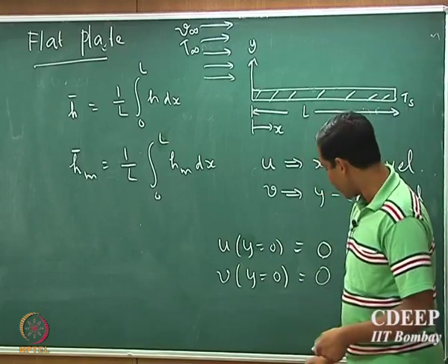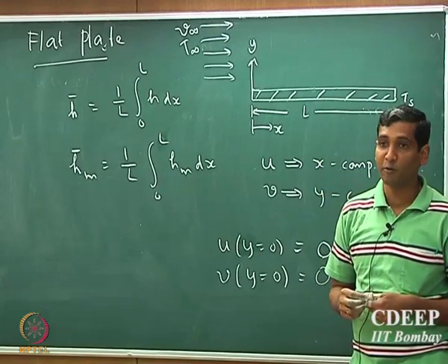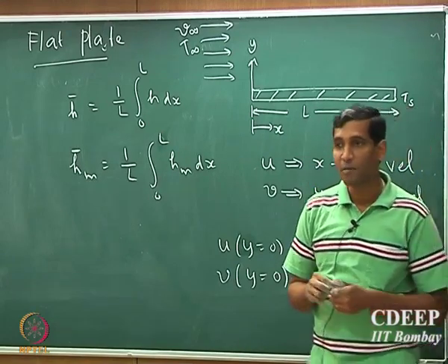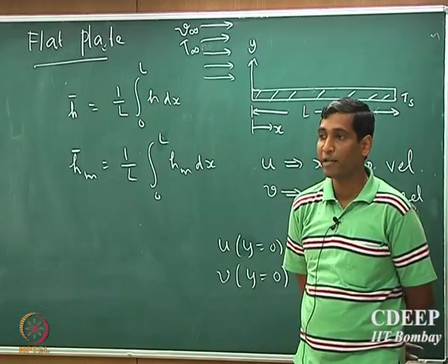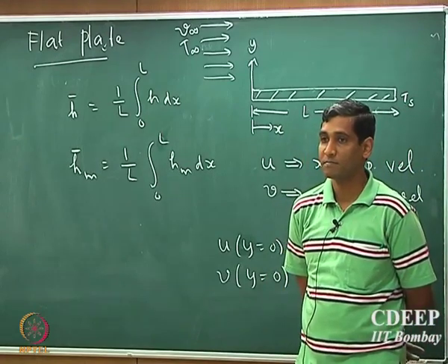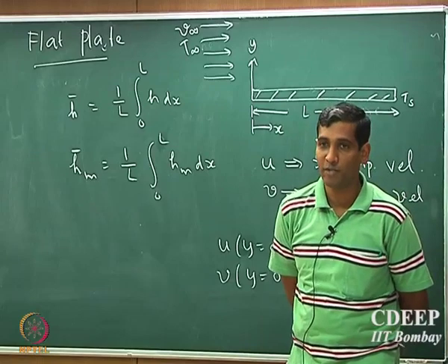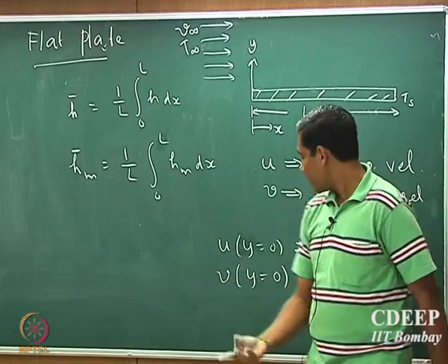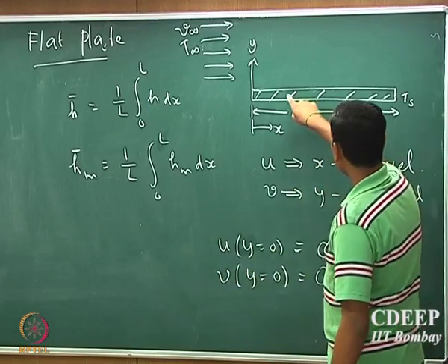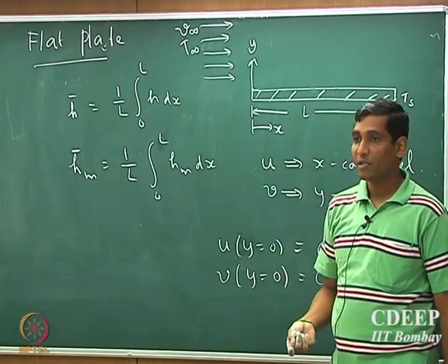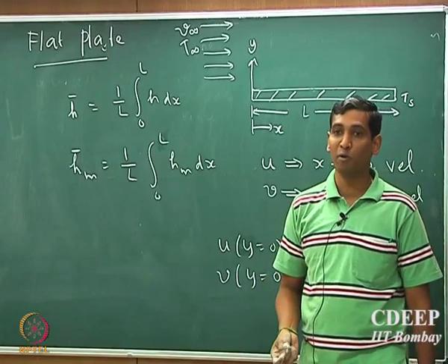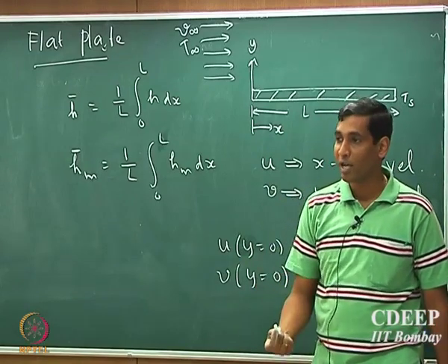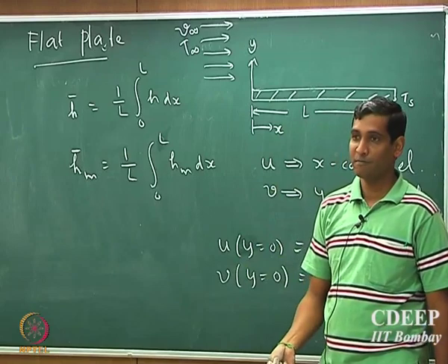So that has an important implication in heat and mass transport. What is the mechanism of heat transport at the boundary? What is the mode of heat transport? We said there are 3 modes, right: conduction, convection and radiation. Because the velocity is 0 at the interface, the actual mode of heat transport from one phase to another is conduction.